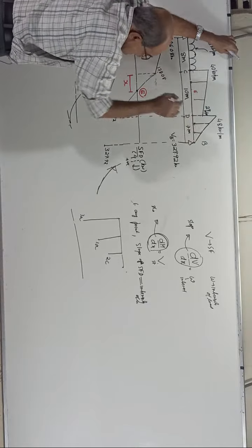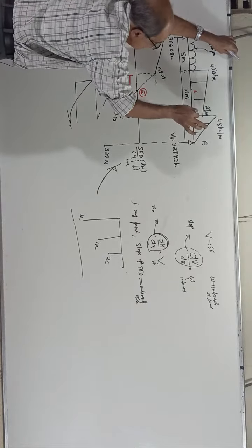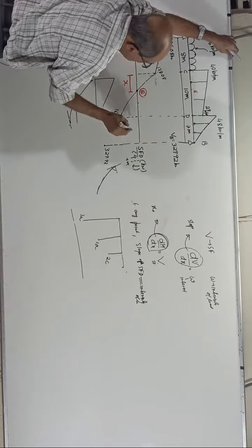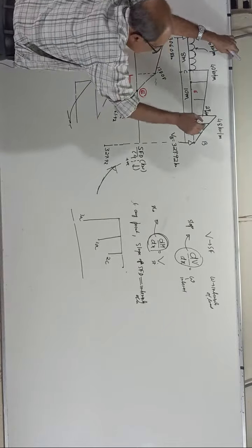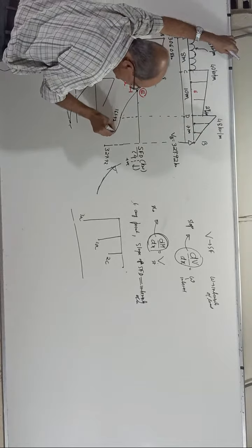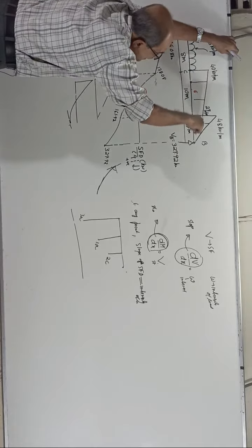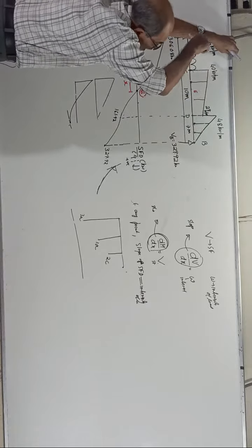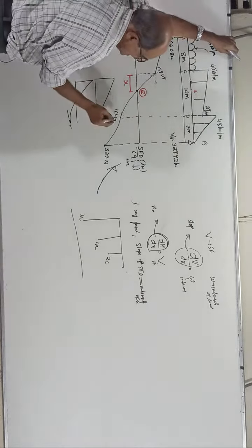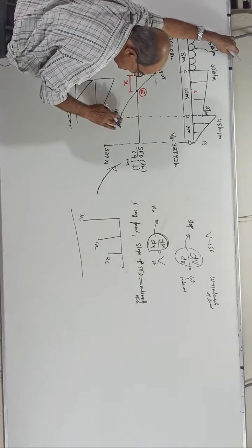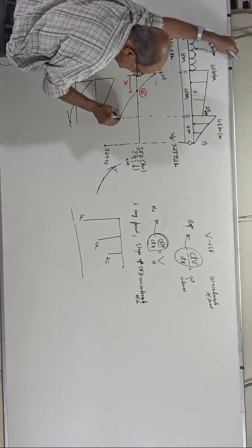here to here, once again a parabola, and important, from here to here, when you want to go, two options for you. See, one of the options, first option this way. This is wrong because, see, as you go this way, what happens now? Intensity of load decreases. But here, as you go that way, slope increases. It should not be steep, flat. So it should come this way.